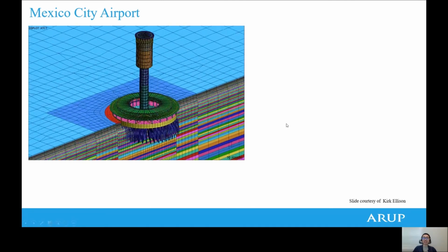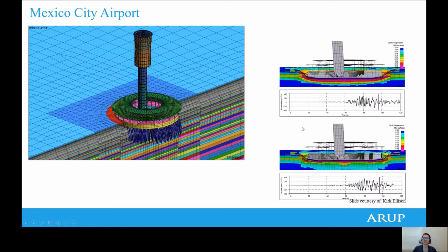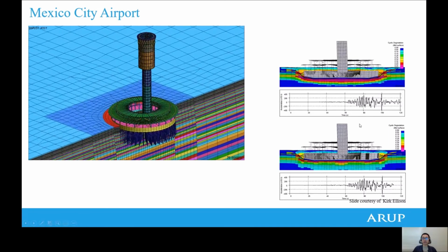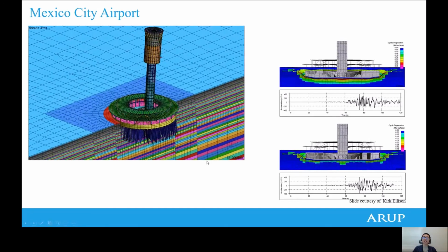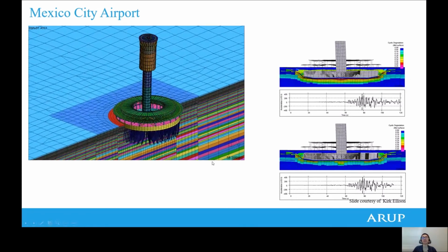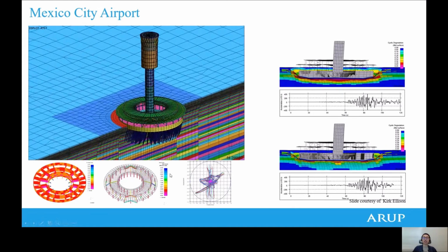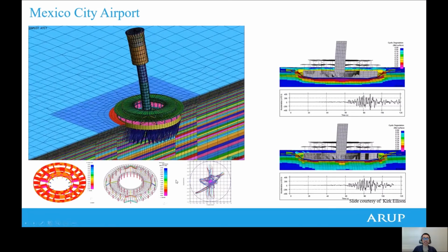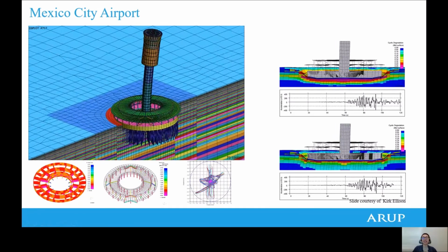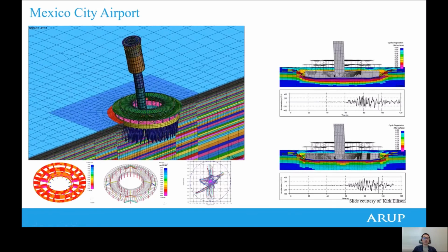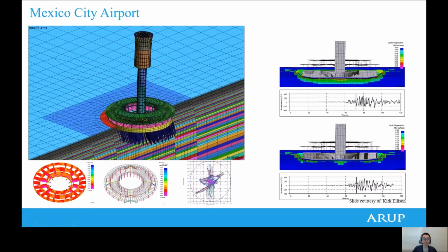And we also did some comparison on the modeling of cyclic degradation of the soil material in LS-DYNA, as shown on the right here, to really investigate the effect on the overall and local foundation area responses. And the analysis was not only used to assess the demand on the soil, on the geotechnical system, but it is also used to extract the structural demands for design, as shown in these sample results here. So in this project, LS-DYNA really plays an important role in design and in understanding how the structure will behave under this kind of very complicated soil condition.